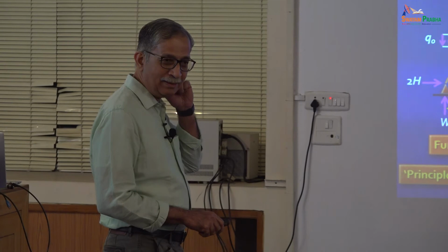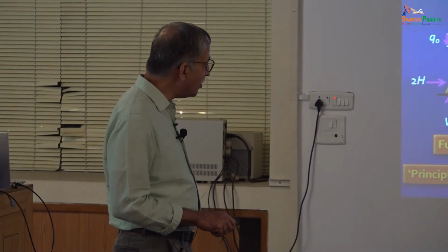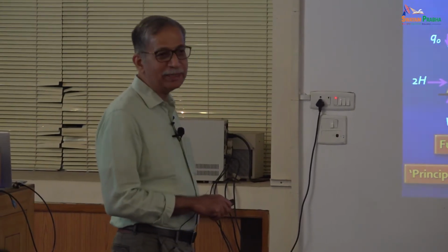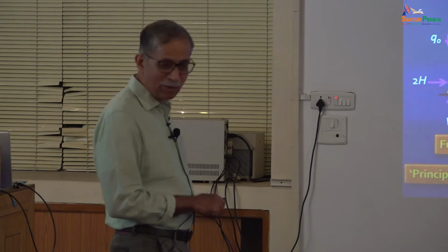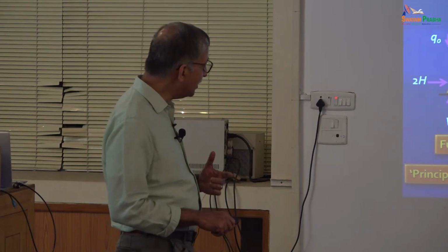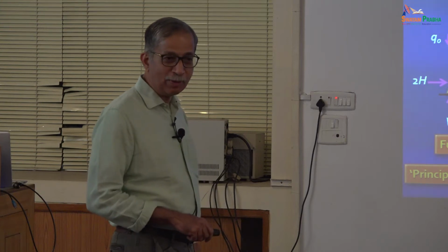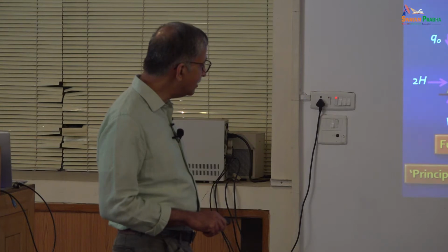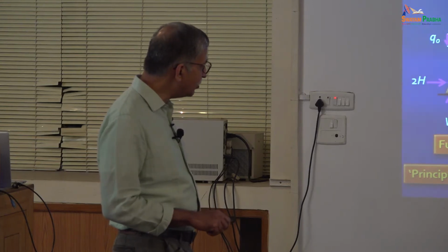And so? It's so simple. H is the same for this loading whether I put this arch or this arch, right? The whole idea of giving a rise to the arch is to eliminate these moments to the extent possible, yes or no? These are sagging moments which get reduced by the hogging moment caused by H into Y, yes or no? How much y should you give to eliminate this moment? You must give this much y.